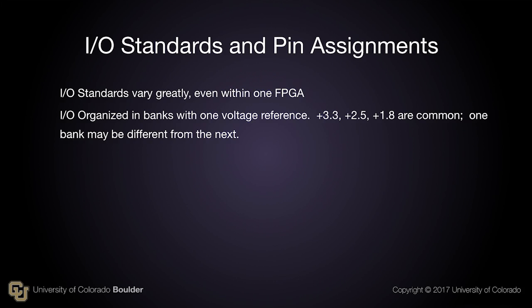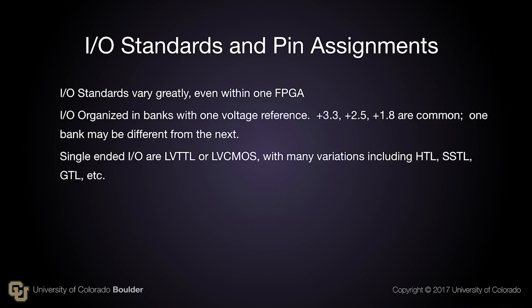The next bank may be different from the adjacent bank. The single-ended I/O are LVTTL or LVCMOS, with many variations including HSTL, SSTL, GTL, etc. There are also differential I/O standards, typically LVDS, but also LVPECL, CML, etc., that require 2 pins per signal.